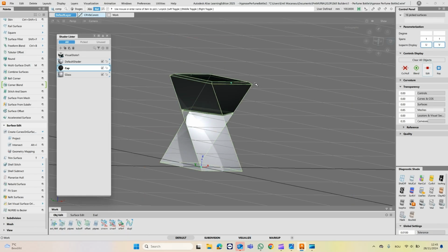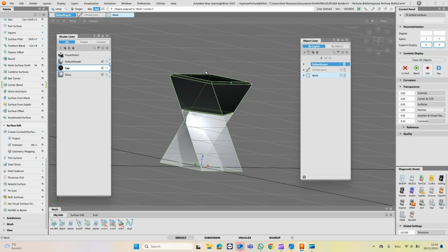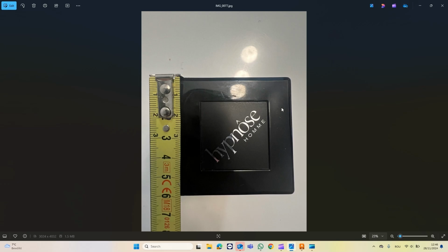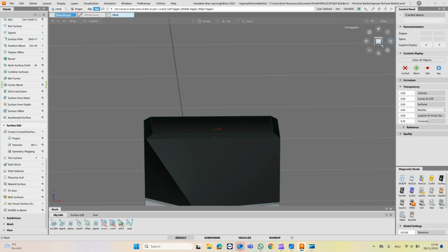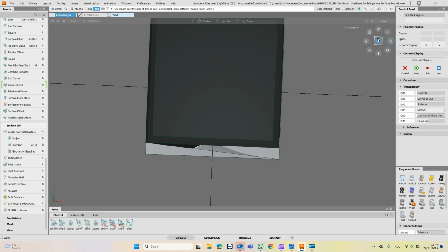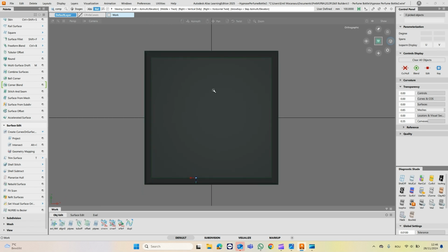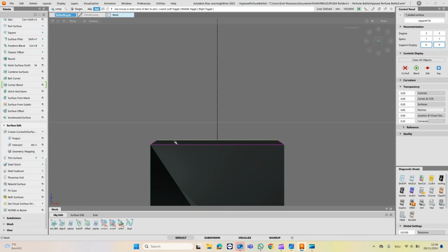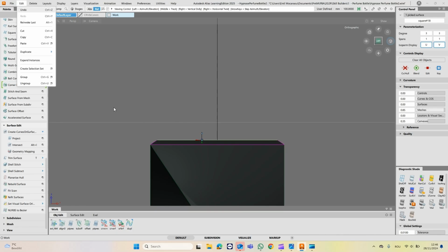All this goes onto the proper layer. That keeps your work nice and tidy. So that's one step closer to that. Now we can see that we've got from that line to that line 1 centimeter. But what I'll do first is this thing here. I'll take that surface and offset it down by 1 millimeter, or let's say 1.5.